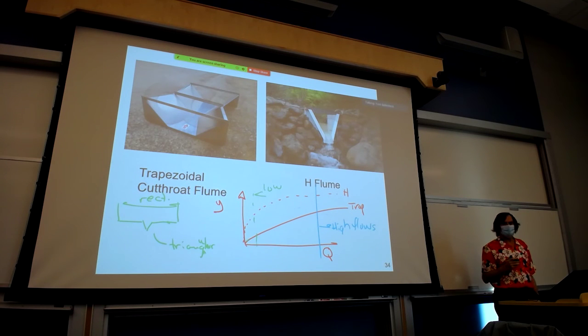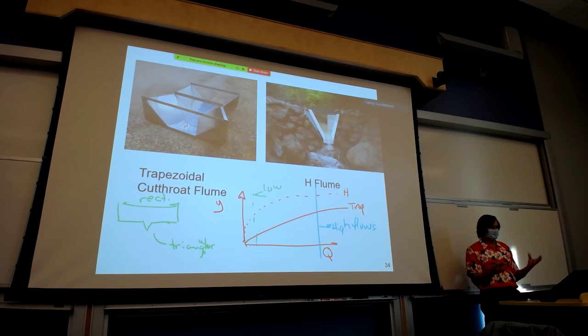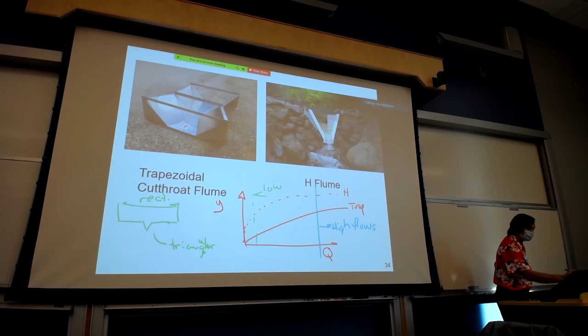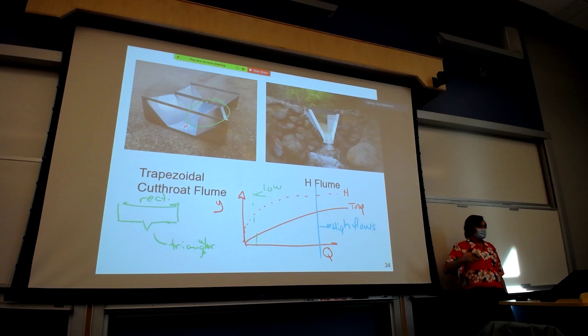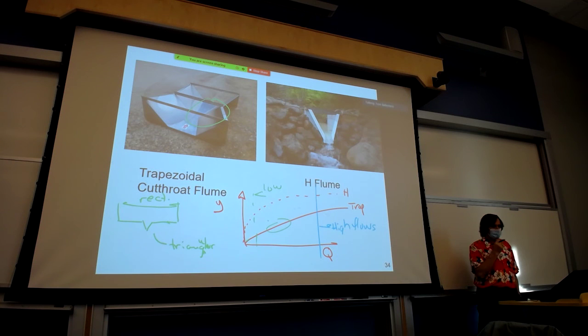And again, in these open channel systems, these flow systems, very rarely is the water just sitting there nice and stable. It's always bouncing around because of waves, because of wind, because of waves created by the contraction itself, just like when you see bow waves and stern waves off of a ship. These features, wherever you have a change in the geometry, create waves. And so the water level is always bouncing around, and you're trying to get an accurate reading of the depth of flow, and therefore the discharge. And if your depth of flow is bouncing around, and you have a very flat rating curve, you have wide ranges in your estimates of the discharge.